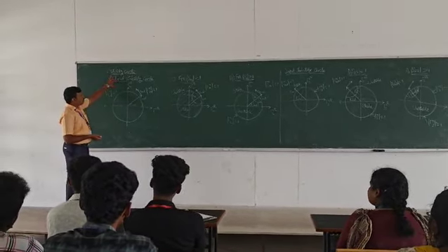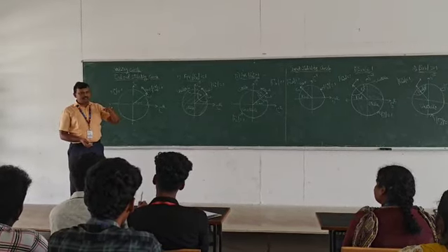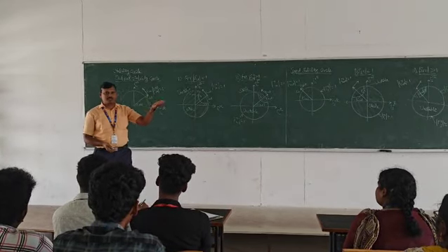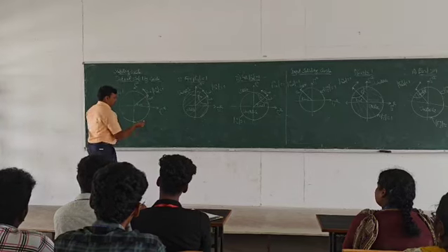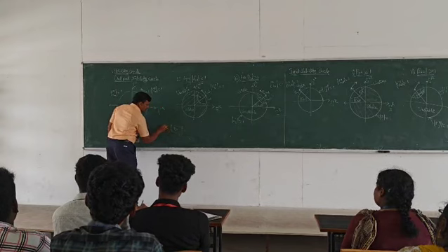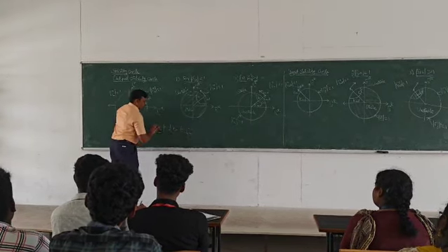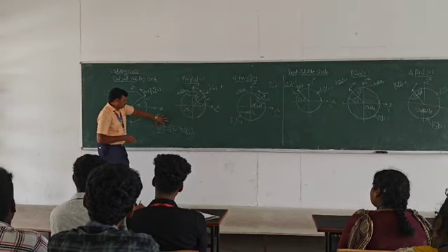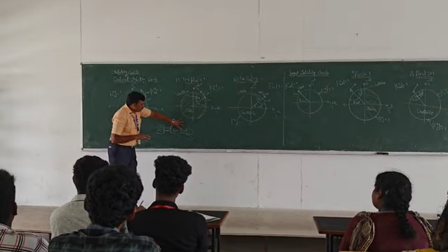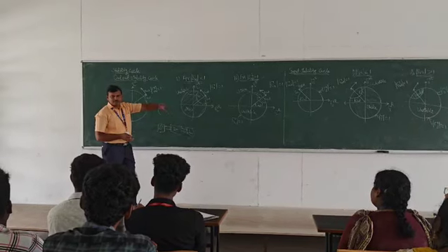First is the output stability circle, and then the input stability circle. If you maintain the input stability circle, that is also maintained in the output stability circle. We know that in a communication chain, this is our amplifier, this is our source, and this is our load or destination. Both should be maintained at the same level, so the source stability and load stability should be the same. Then the amplifier should be matched to your source and also to the destination, that is, the load.